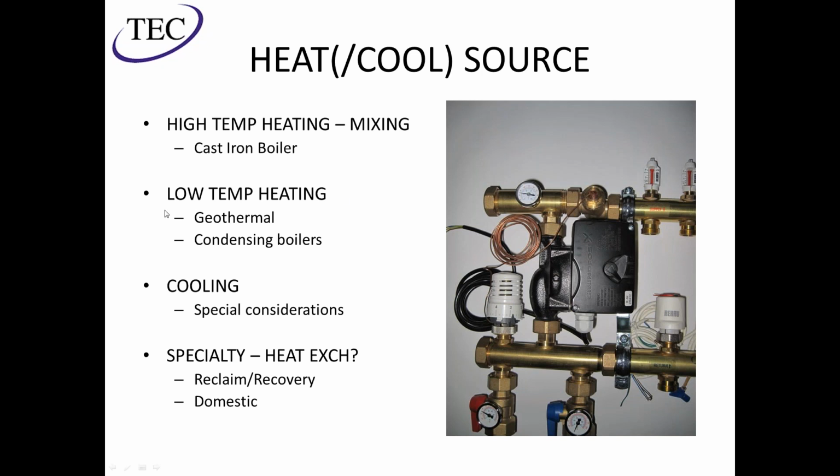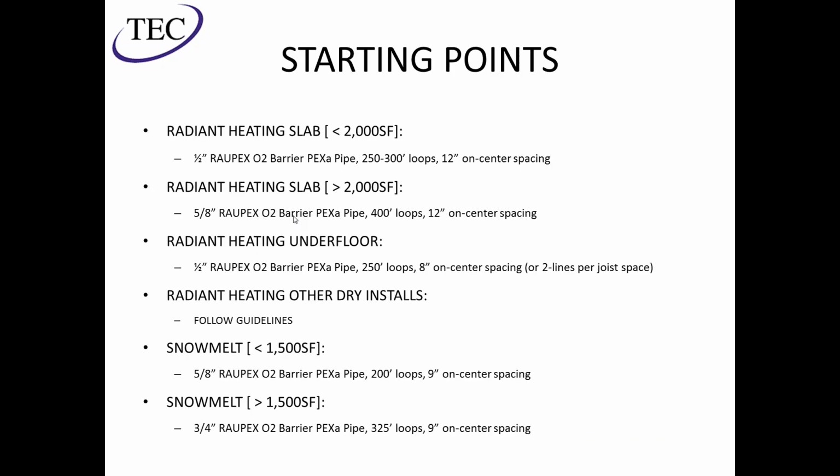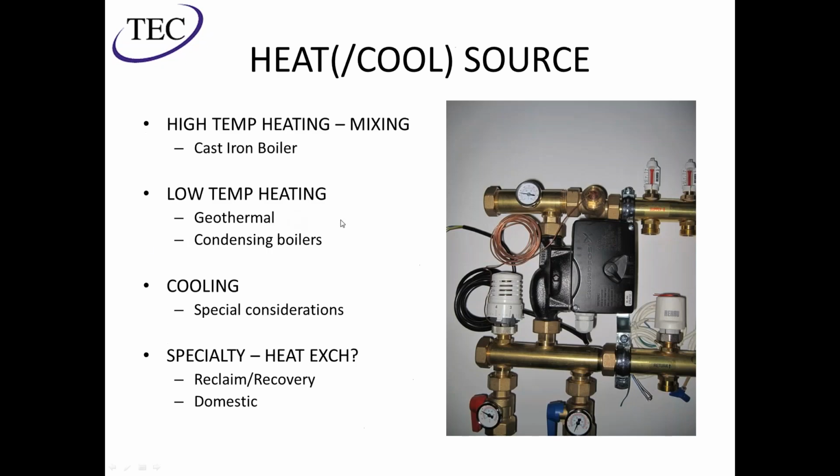Low temp heating, that's what you're going to actually be putting through the floor, but as far as the heat source, you might have some low temp sources from geothermal or ideally condensing boilers. I shouldn't say ideally, geothermal is obviously ideal as well, but a condensing boiler versus a high temp boiler is definitely ideal.